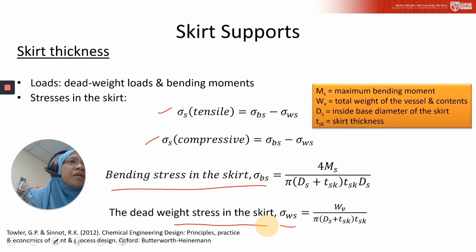And the other parameters needed are the maximum bending moment, total weight of the vessel and content inside, base diameter of the skirt, and the skirt thickness.